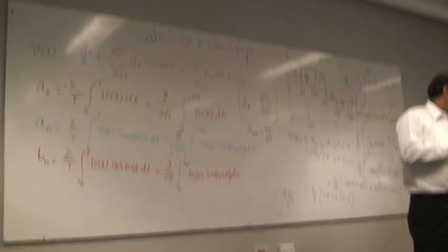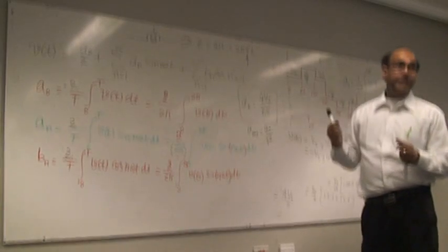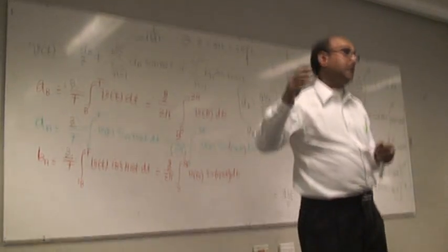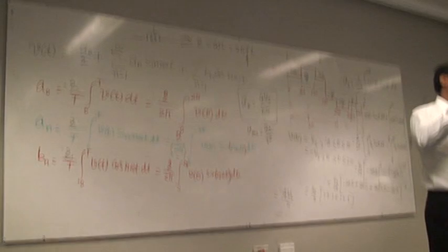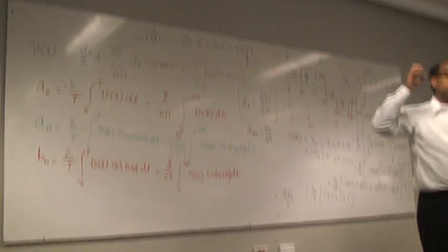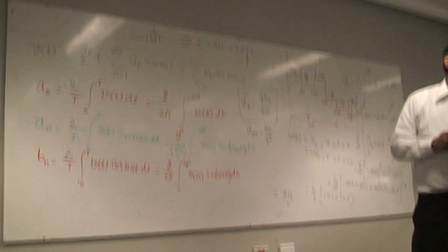But there was an inductor, and ideally that inductor kills the EMI, electromagnetic interference. When you have a pulse coming from an external place, if you have an inductor at high frequency, usually the noise is very high frequency, so the inductor will apply a huge impedance. That will eliminate the noise coming from the outside source.